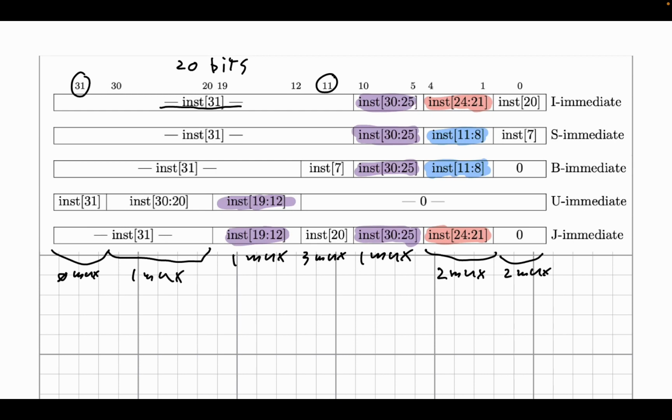And this is such a serious degradation of our performance that quite unexpectedly, this can actually be the slowest thing in the decode stage of the pipeline. This can actually be the weakest link. The limiting factor is just the fan out that's associated with sign extending an immediate.